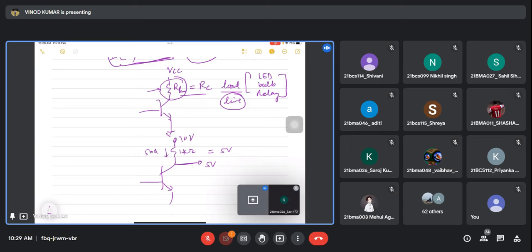So in a nutshell, practically, suppose this is 10 volts and here is 5 milliampere current, and this is a 1 kilo ohm resistor, then the drop across it will be 5 volts. So how much is left here? 5 volts, isn't it? Yes. And if this is 10 milliampere, how much will it be? 10 volts drop. So what should be the output? 0. VCE is 0. That means this is the IC saturation basically. The transistor is moving into saturation. The VCE value is 0.2 in saturation.